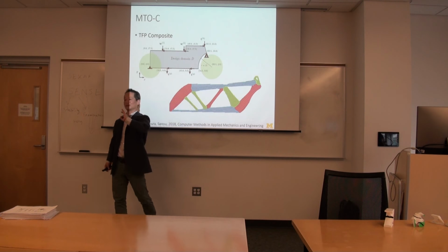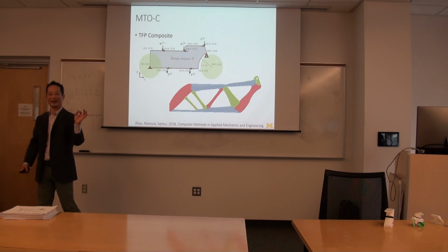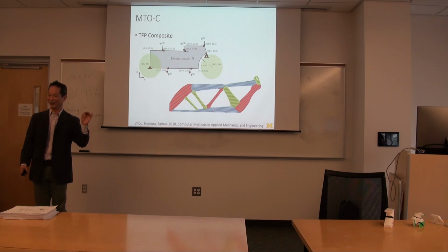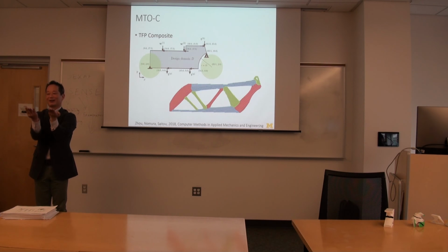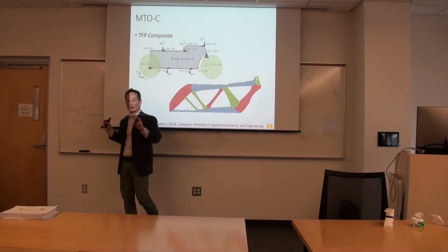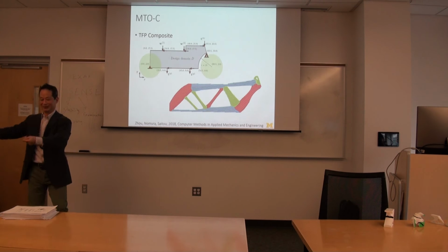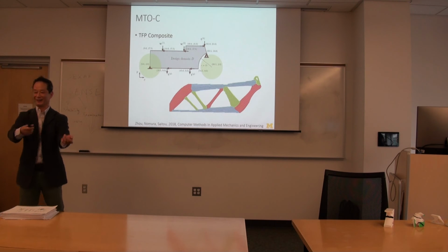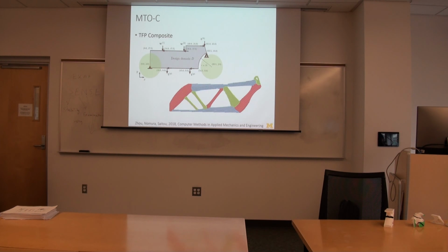In this case, the number of distinct fiber orientations is what we consider as a component, not the physical connectivity between two components. So these are really one component from the composite manufacturing viewpoint. This is one piece you're cutting and then placing. Okay. And so that's really another tweak of the concept of component applied to this chosen manufacturing process.